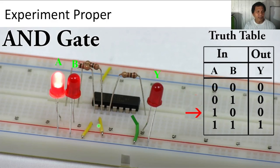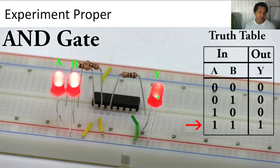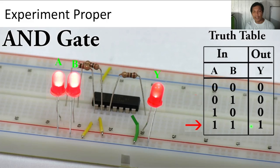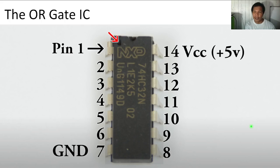Because if you multiply the input, 0 times 1, that is still 0. Okay, now going back, so if LED A is turned on, B is turned off, that is equivalent to 1, 0, the output will still be 0. Move on. If all inputs are logic 1, that is 1, 1, then the output will be logic 1 also. So that's the property of the AND gate. Okay, you have to do that in your Tinkercad or your real IC 7408.